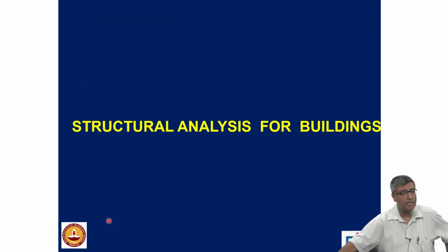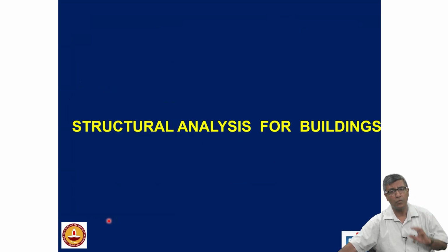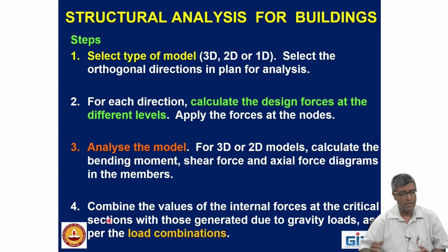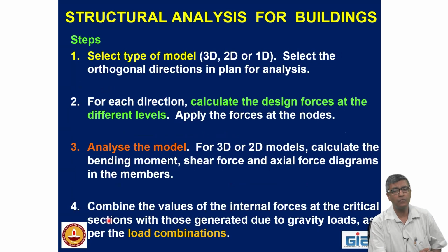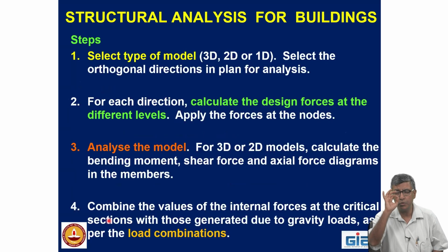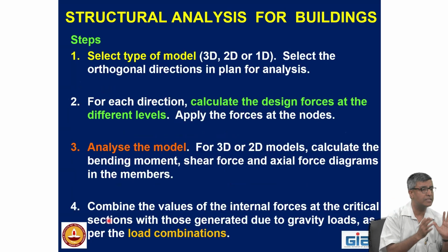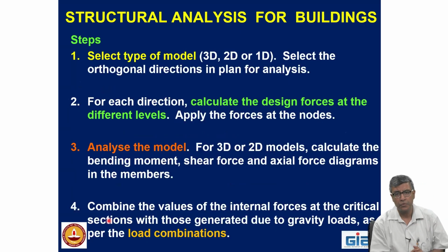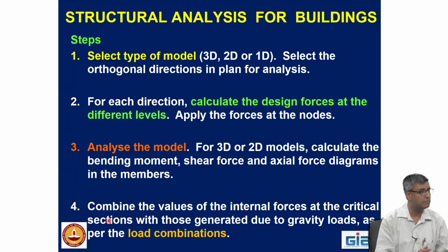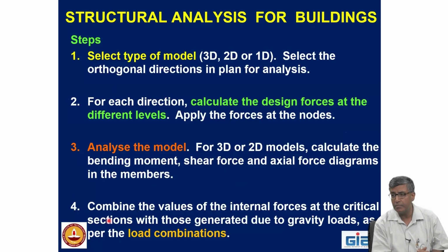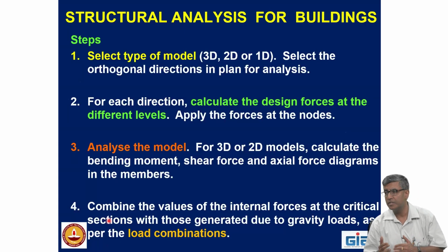Now, coming to the structural analysis, now once I know these forces, then how do I do the analysis? First, I have to start with a model. What today you will be doing is a stick model, one-dimensional model. But I need to know the forces. Next, you can go for a 2-dimensional typical frame, where in your undergraduate you have studied the portal method or the cantilever method, and you can do it by hand for a simple configuration. For a more exotic type, you have to go for a 3-dimensional model.